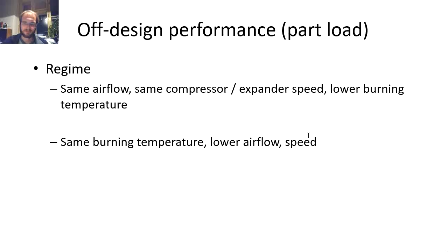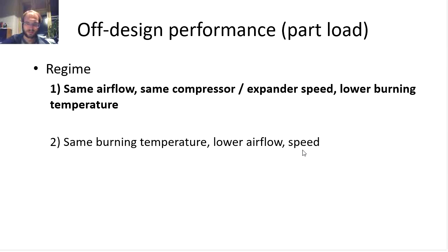The second regime which comes into consideration is having the same burning temperature, and it could be achieved by lower airflow, that means lower speed of the compressor. Now we will have a look at the first option, meaning having the same airflow with lower burning temperature.